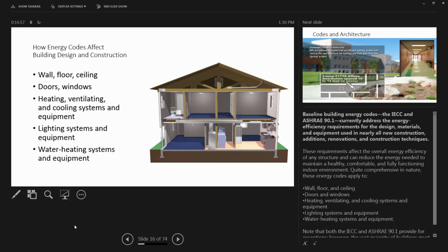Very little. So we'll talk more about it, but basically R value is the resistance of a material to transfer heat. So the higher the R value, the more resistance, the better thermal properties a material has, and the code sets those minimum values. So they'll say that a wall has to be at least R21 or R19, depending on your climate zone.